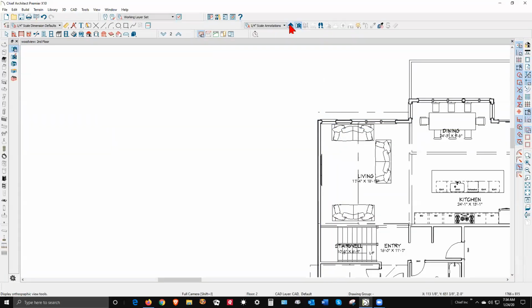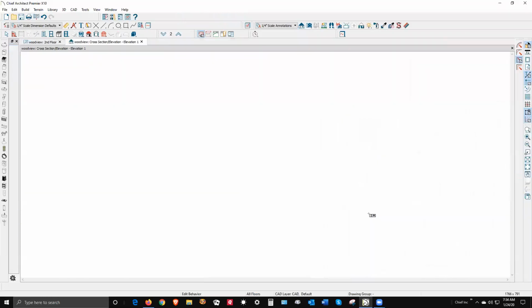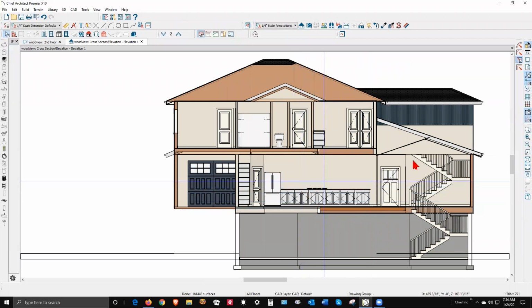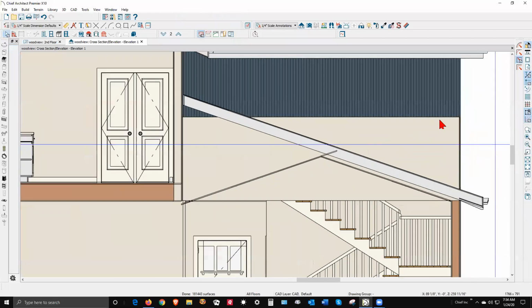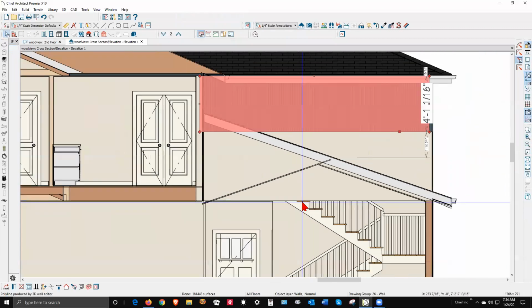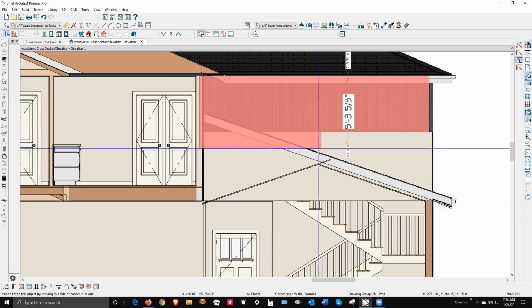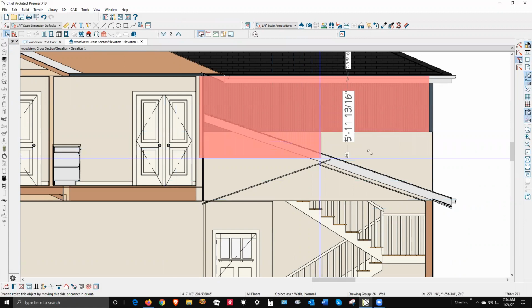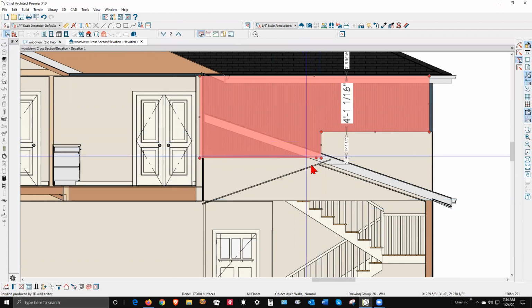I'm going to go back. Sorry this is taking so long, but you know, these things take as long as they take. Okay, so now I'm going to take this upper wall layer and use the break line tool and break it in the center. I'm going to bring this down to here, just so it doesn't show in the inside of the house, but it shows on the outside. Bring that down to the roof.